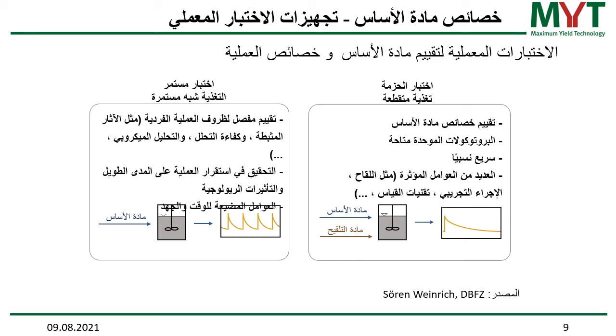But the results have a certain standard deviation, so the precision of a batch test is not very high, in particular if you want to transfer the results to a full-scale application, to a continuous operation. This is due to the fact that there are many influencing factors like the inoculum, experimental procedure, and measuring techniques. That's why the batch test is the more common, but actually only the second best choice in testing substrates.